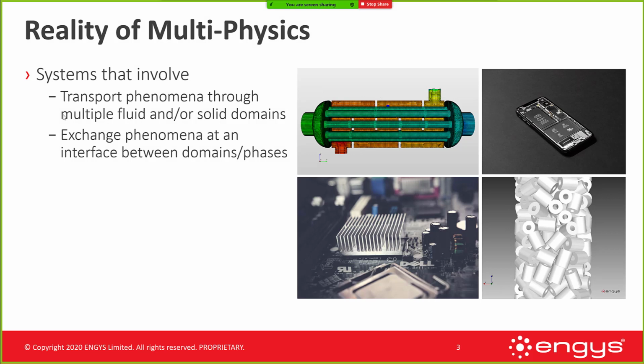Multi-physics is kind of the grand challenge of CFD. Everyone wants to do that, I think, when they first start with CFD, and it's very complex, to say the least. We could define multi-physics as systems that involve transport phenomena through multiple fluid and or solid domains. So that's heat, mass, momentum. Then there's also this idea of exchange phenomena at an interface between these domains. So mass transfer limitations, energy transfer limitations.